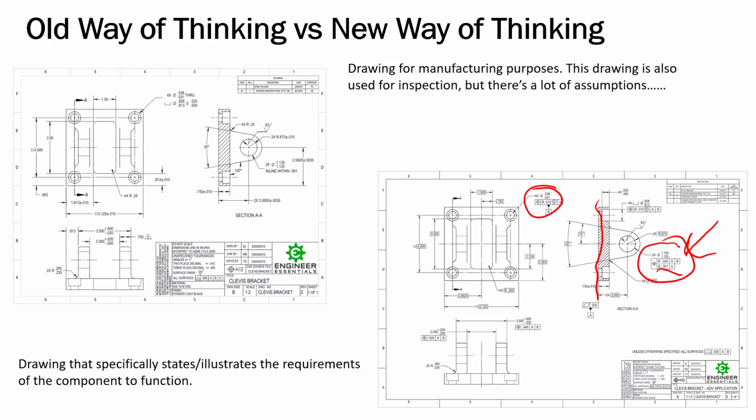Normally we use baseline, so we've said, well, this is where we're going to pull all of these dimensions from, so that we're 9/16 up, 4-inch square pattern here. We're coming from that bottom frame. With this type of dimension, we could have come off of right here, but then over here on the side, we would need dimensions related back to the center, using this section view as an example. We could have done that, but we still would not have cylindrical tolerance zones like we do with GD&T. It would still be a much tighter control.